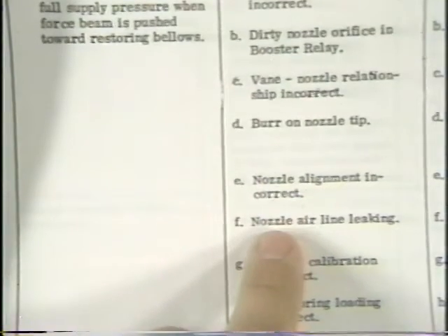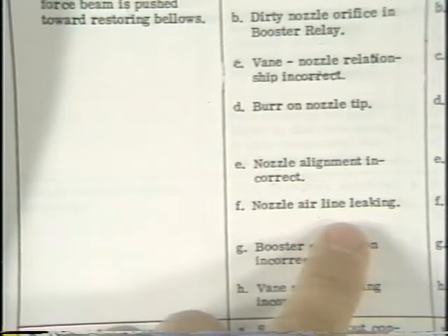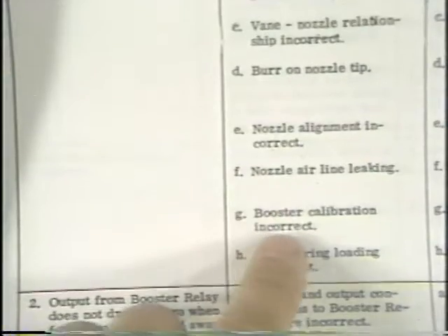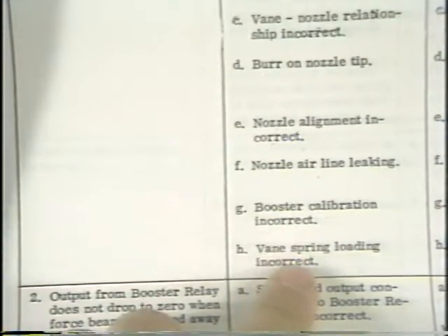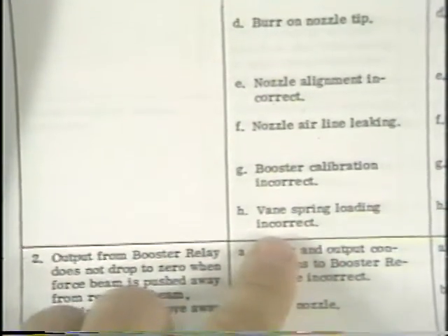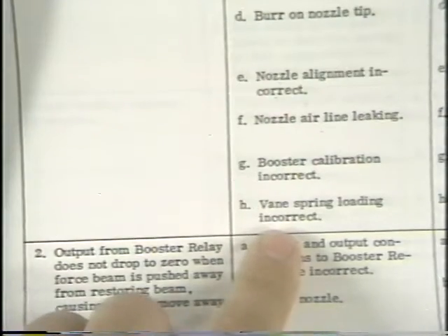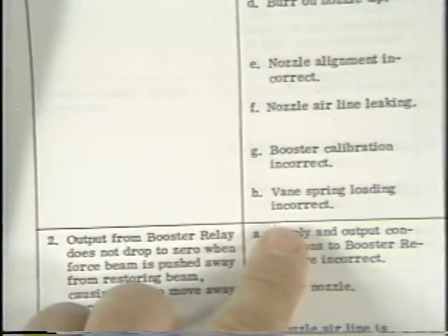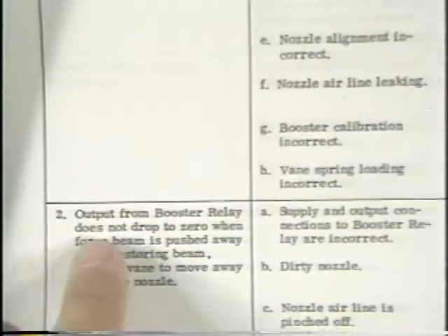That's a possibility too. Let's see. Nozzle airline leaking. All of those things are related to the nozzle. Booster calibration incorrect. No. Vane spring loading incorrect. No, I don't think so. Let me see what else I've got while I'm looking through this chart.